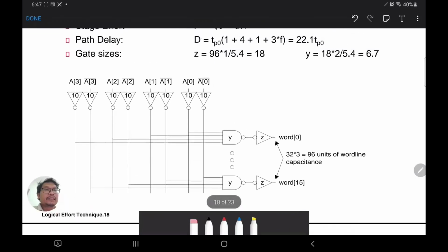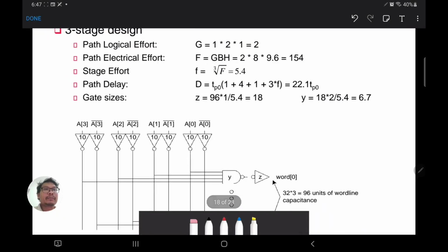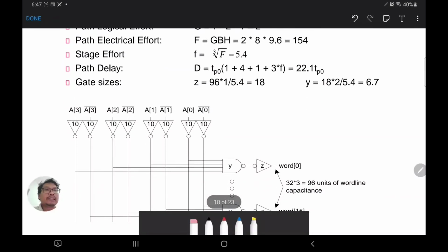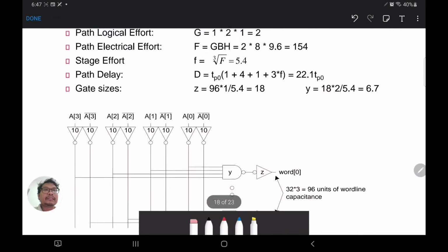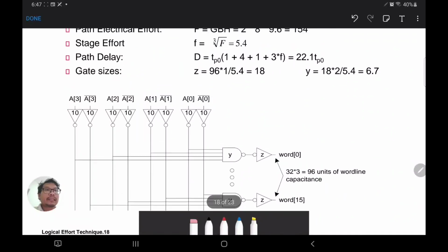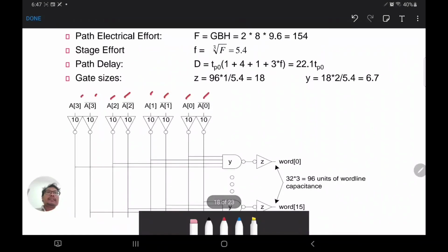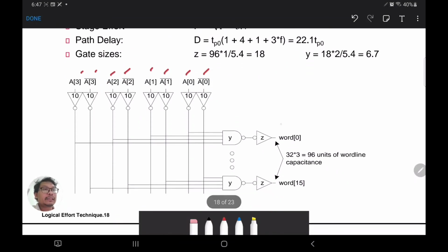Okay, so here is a partial block diagram of the gate level implementation of the decoder. Basically your address is here. You have A0 and A0 bar, the complementary of the address. So 4-bit A and 4-bit A bar, and then the output is here.